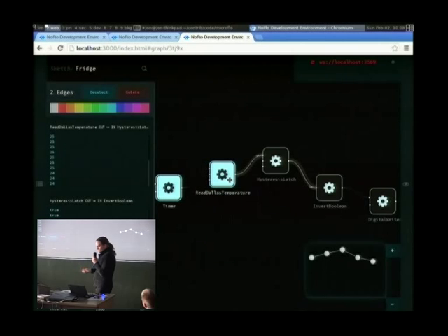It reads the temperature from this digital temperature sensor. It goes through a hysteresis latch so that I can have a different threshold for when to activate the cooler than to drop it, so that if the temperature fluctuates around something, then it won't go on, off, on, off, on, off like crazy. And because I wanted the output to be on when it's too cold, I had to put an invert boolean in there. And then I just write that status to the output, which is, in this case, the LED. That would normally be the relay for the output.